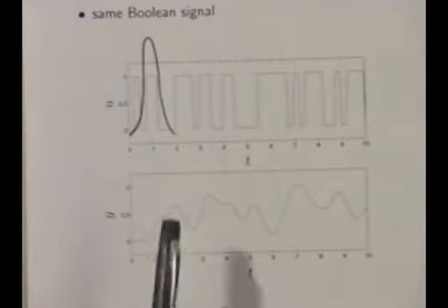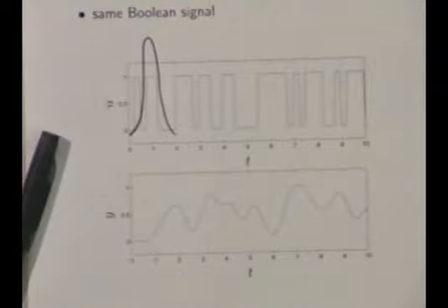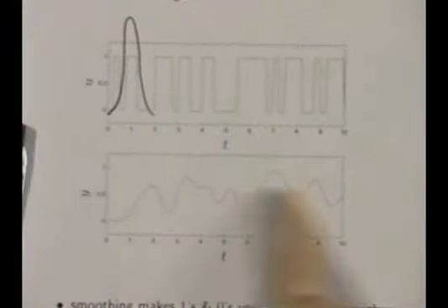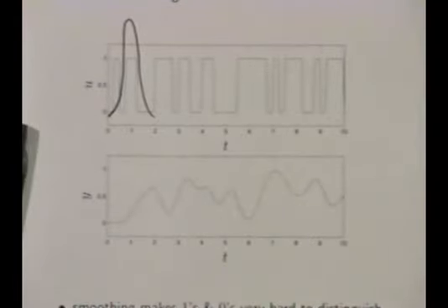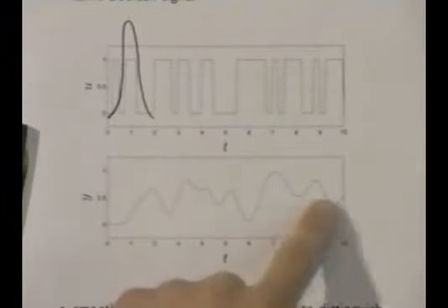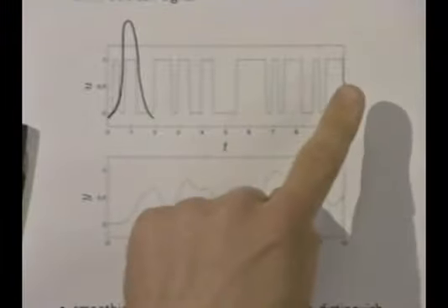This makes perfect sense because this system is smearing together what happened at the input over a 2-second interval. But 2 seconds catches 8 bits of information. And you get this signal here, where everything has been smeared together. So it's not at all easy to see the input signal from this. Now, the truth is, by sophisticated signal processing, we can make a very good estimate of what the input was from this. But it's not simple like just asking whether the signal is above 1/2 or below.